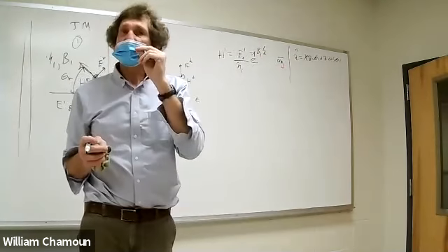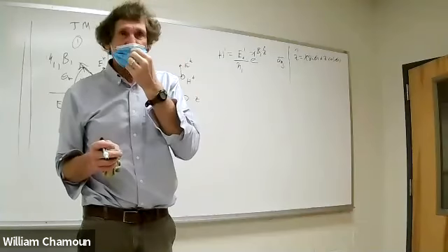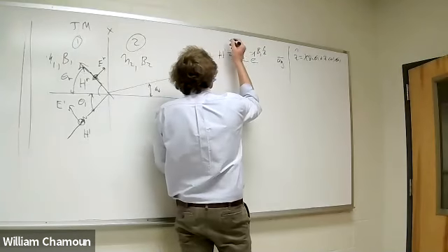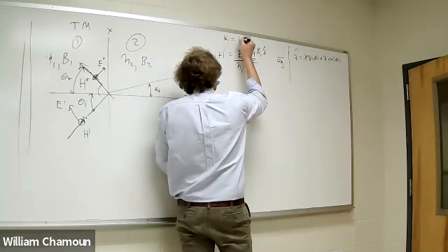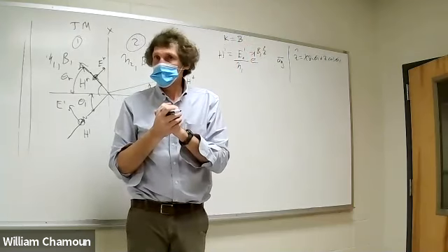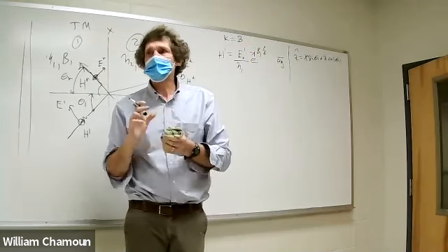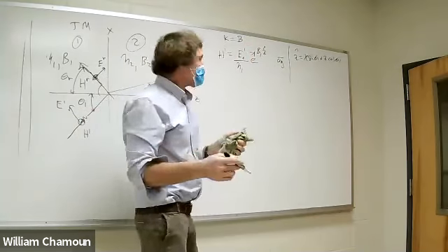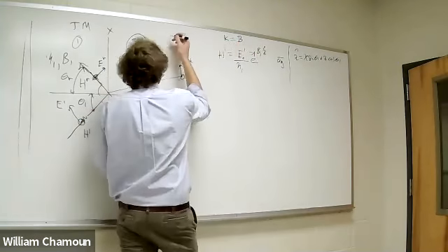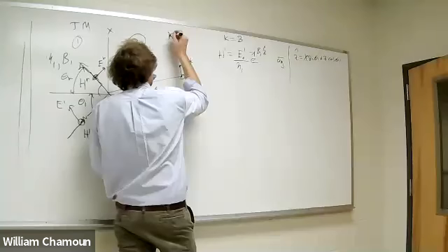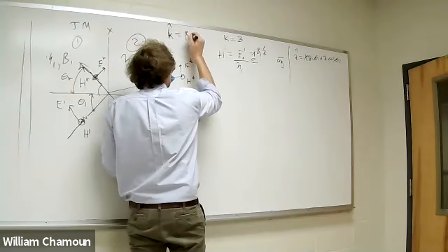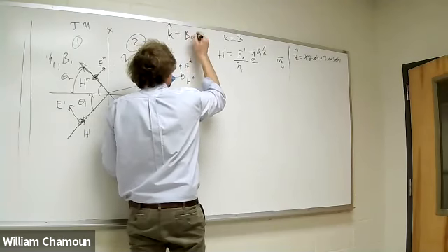This is important. One other thing that happens is, oftentimes in other books that are useful in electromagnetics, they don't use beta. What they'll use is the symbol K, which is equivalent to beta. They're both wave numbers, the units being radians per meter. But then what they'll do is also give K a vector sense. So what they'll do is they'll take this information and say that K vector here will be equal to beta, and then it'll have a unit vector in the direction of propagation.